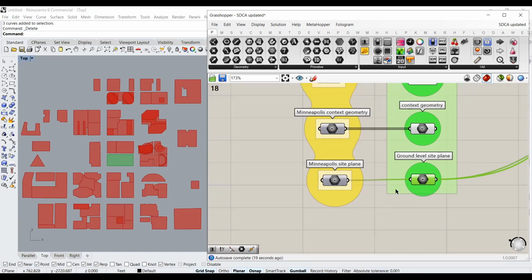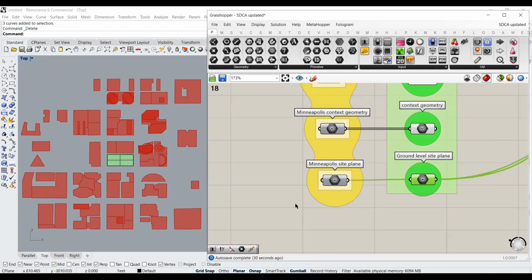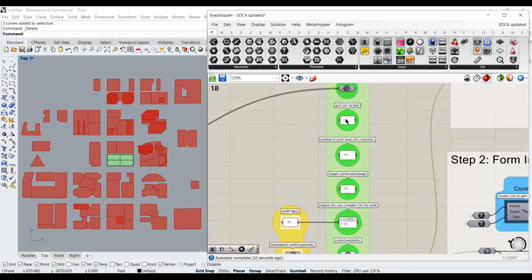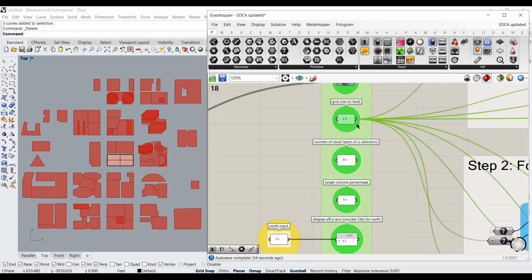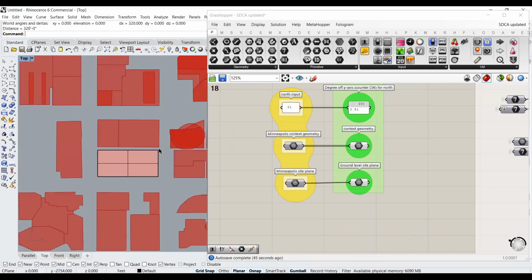And a thing about this surface, that's all it is, just a surface that's brought in. But the dimensions of it need to be perfectly divisible by the grid size. Otherwise, you'll get some remainders and things might not work properly. But if I measure this, it should be divisible by 10 because that's my grid size.